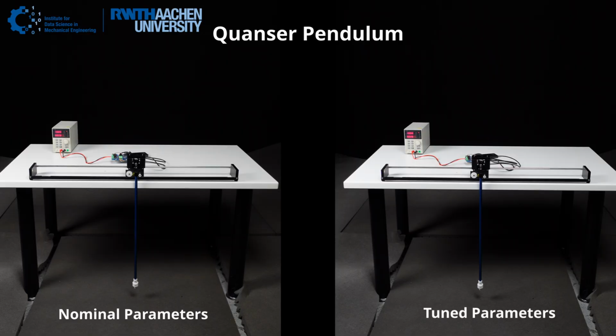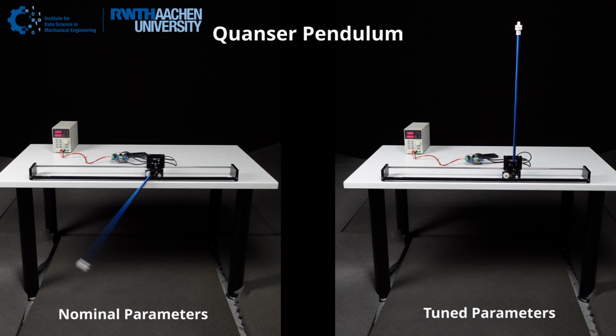We initially sample a dataset from an MPC that considers parameters of a cart pole system given by the manufacturer's datasheet. A neural network that naively imitates this MPC does not achieve a swing-up on the real system that has different parameters from the datasheet. Instead of going back through the lengthy process of changing the MPC and recomputing dataset and neural network, with our method, we can now predict how the controls would change given the real parameters. Thus, our approach successfully performs the swing-up and stabilization.